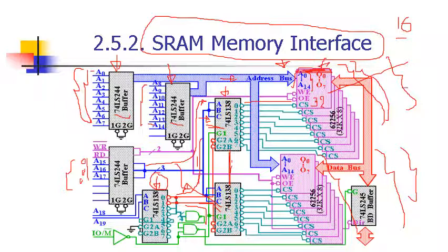Each group, upper or lower, requires a 3 to 8 decoder. Because we have 2 decoders, we have to use a third decoder that selects between the upper decoder and the lower decoder. And we see that all address bits used are buffered.